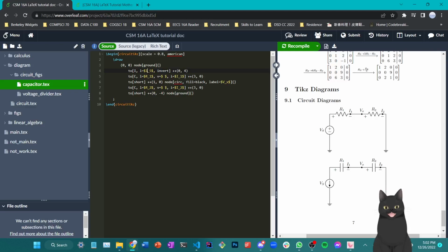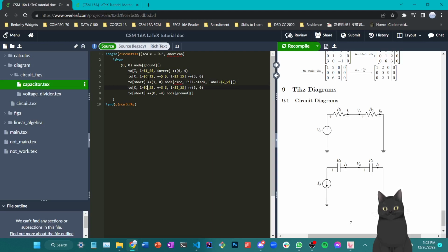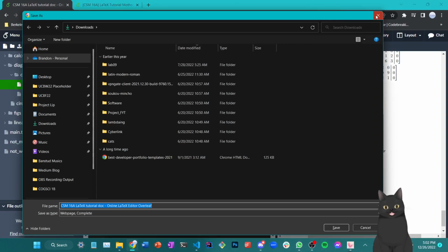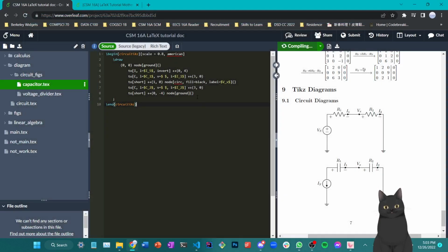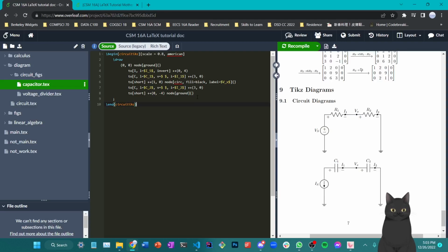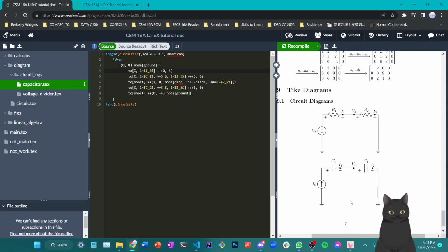And yeah, we do need to change our label as well. Oops, almost accidentally saved this. Accidentally saved this again. Let's use Ctrl Enter instead. Okay, and current source should not be inverted in this case, so let's adjust that a little. Okay, that works out. And last but not least, you can also use the I equal and V equal nodes on your current source, as well as your voltage source. I'm just going to demonstrate this with the current source.